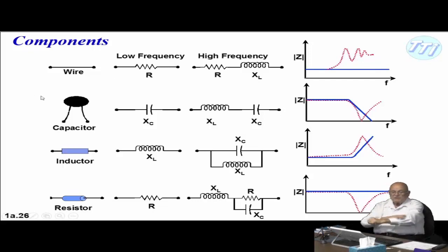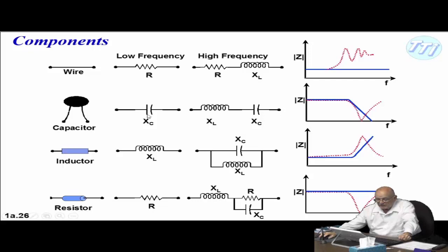Take this capacitor. We still use a lot of capacitors like this in circuits. Many of them are board mounted or right on stripline or things like this. The reason, of course, is to reduce the length of the wiring, which you can see here. This is our symbol for our capacitance. And then again, what happens here is you've got wires here. That creates the inductive aspect. And so we end up with effectively a tank circuit. The Z would normally go like this, down. But because of that inductance, it creates that red situation where we end up with it forming that shape. And these can interfere with circuits, create problems.